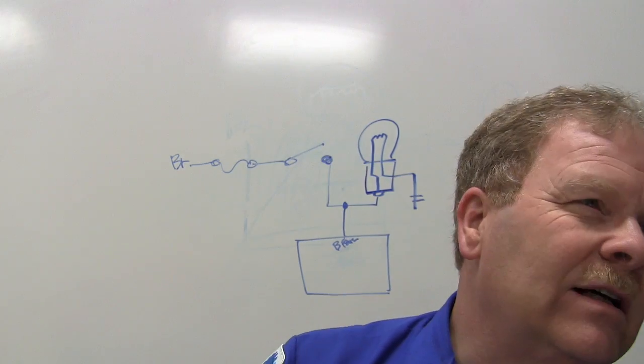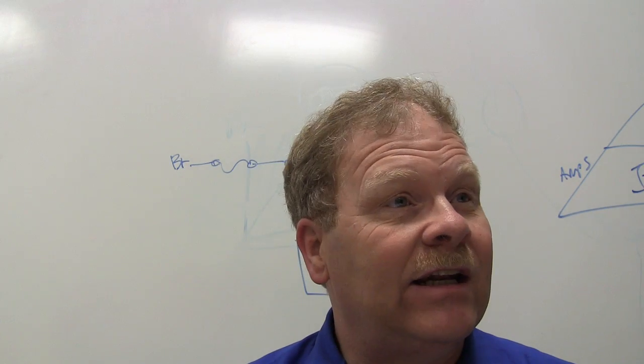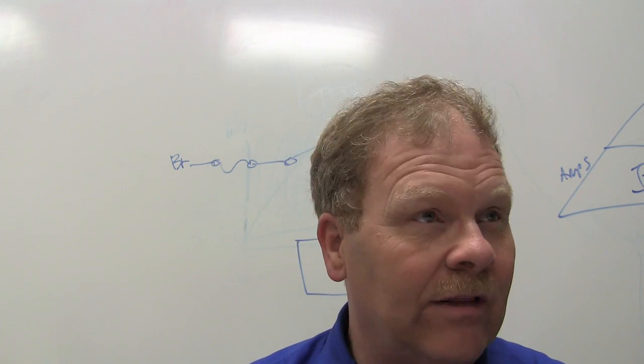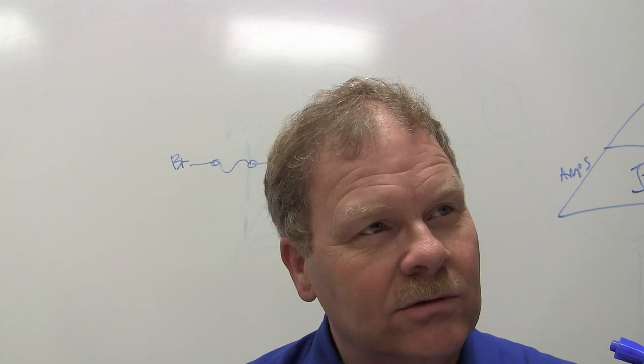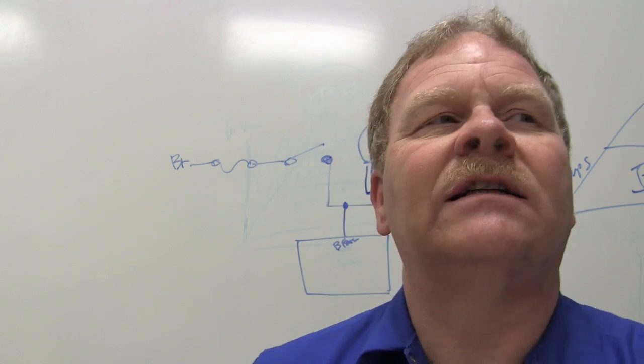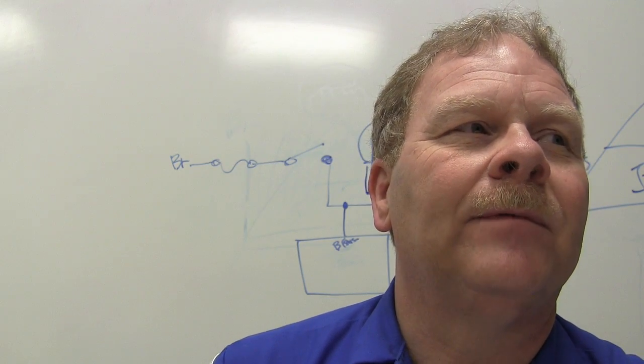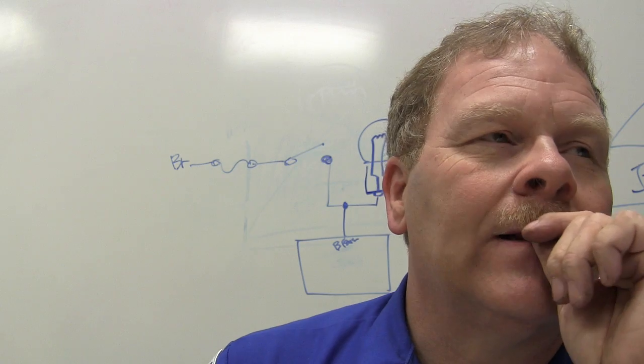No, what happened was, when we got ready to start it a while ago, it was cooled down, it would go and it was not starting. Didn't you hear that? We got a scan tool, we put it on there, and it said no crank sensor. Now, we know our first crank sensor was bad. Melissa, how did we know the first crank sensor was bad? Because when you heated it up, it lost power at a certain degree.